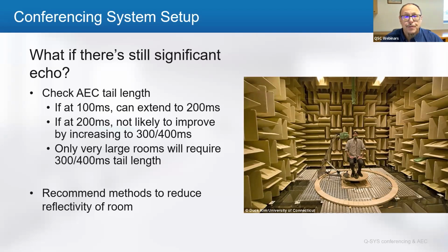If you have one zone of speakers and multiple wireless mics in a system that are reinforced, do you do an AEC mix-minus to route each mic to all other mics' references? Well, if you have only one zone of speakers, mix-minus is really for when you have multiple zones of speakers, depending on where mics are located in reference. For instance, if I'm doing mix-minus, that means the loudspeakers over my head aren't going to reproduce my microphone sound.